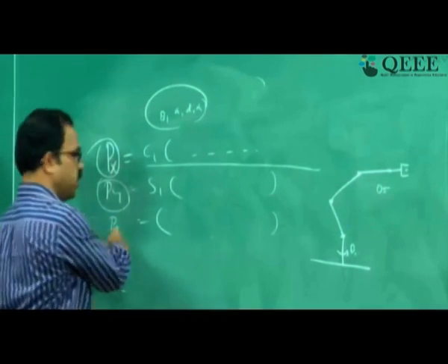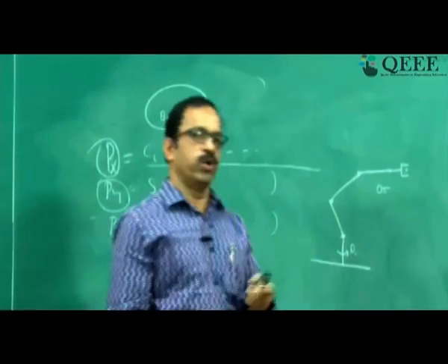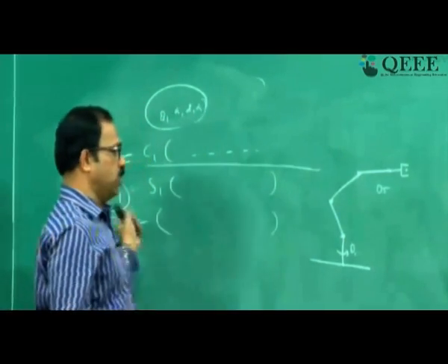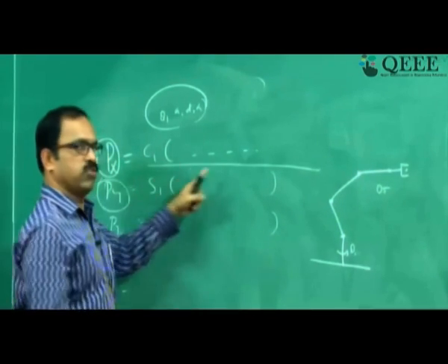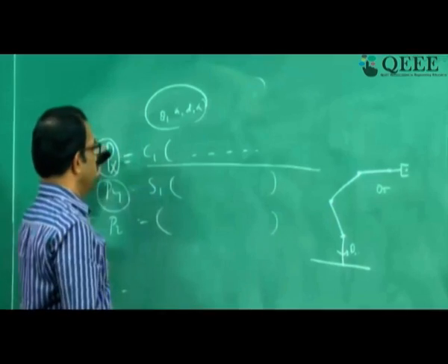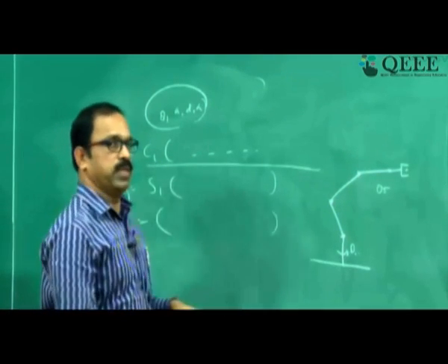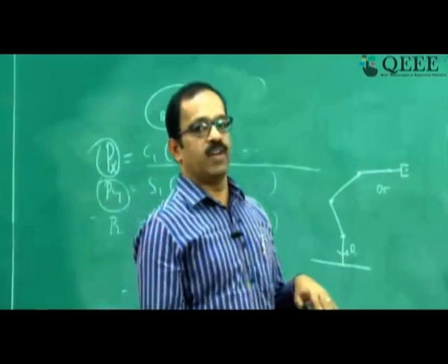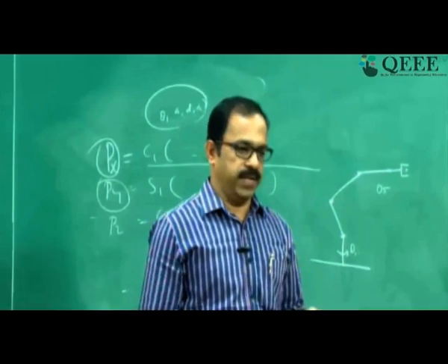This is the position, and the 3 by 3 matrix on the left side gives you the orientation of the tool with respect to the base frame. So that completely defines the kinematics of the manipulator with respect to the base frame in terms of the DH parameters. This is how we develop the forward relationship for a given manipulator.